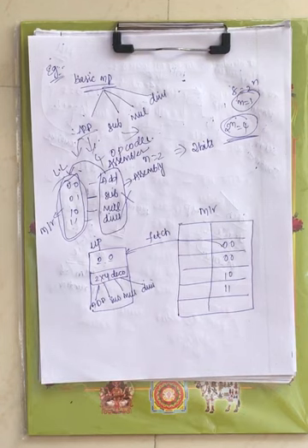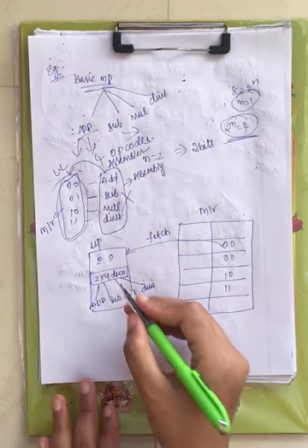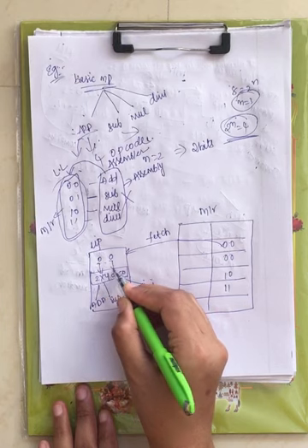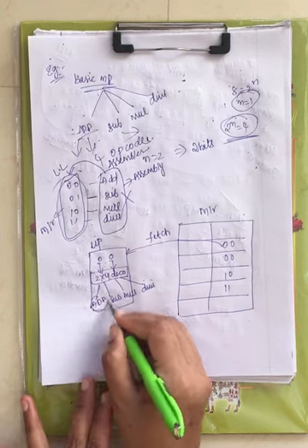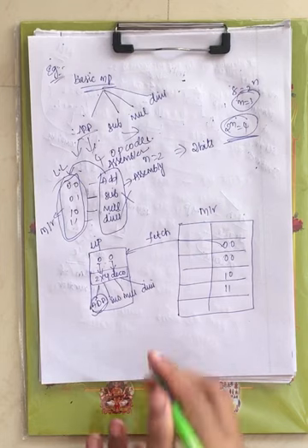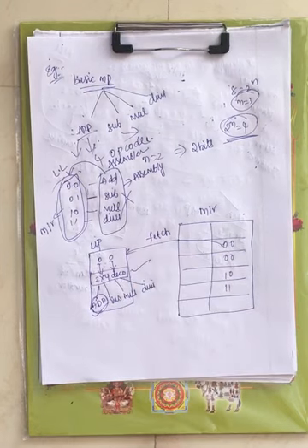First it will fetch the instruction from the memory. This is given as input to the decoder, right? What will the decoder do? It will decode. For 00 you have which one? Addition, right? Now this is executed. Here you are decoding the opcode using the decoder, and here you are executing that, right? You know the operation of a decoder.